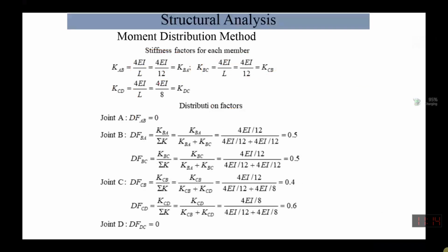That's why we calculate the stiffness factors for each span. This is our span, one stiffness factor over here, and one stiffness factor we calculate for the other part. This is KBA and KAB, remember. This is how we are calculating it. So we have calculated the stiffness factors. Then we will find out the distribution factor. How many distribution factors will we calculate?